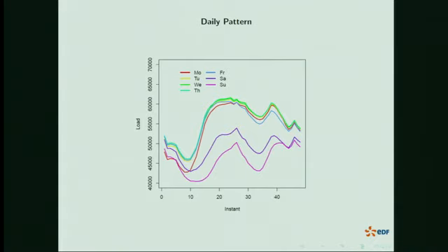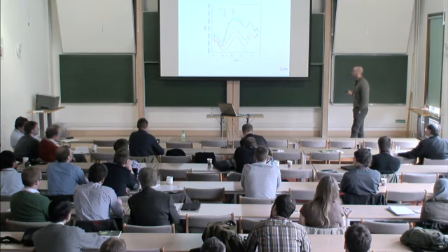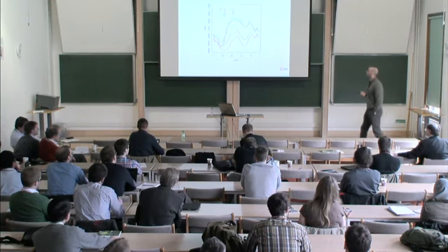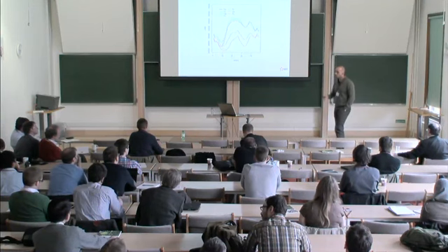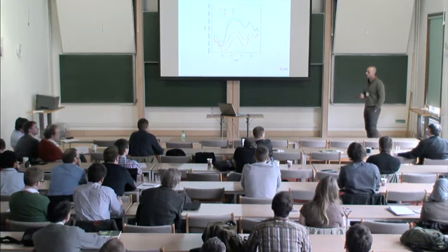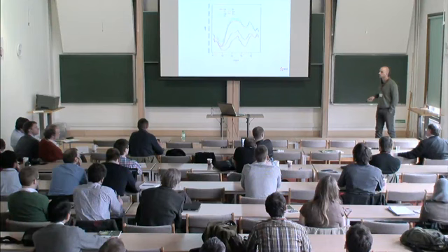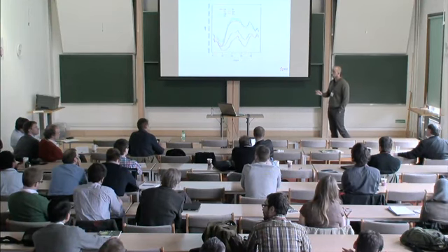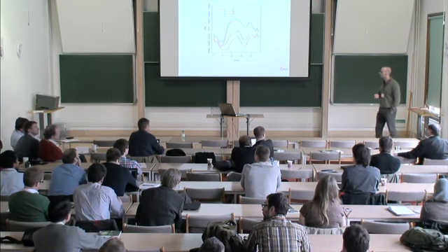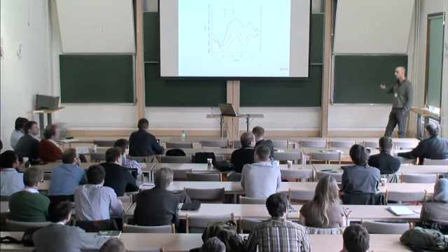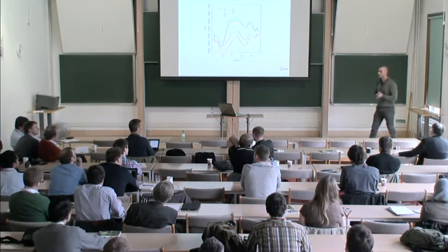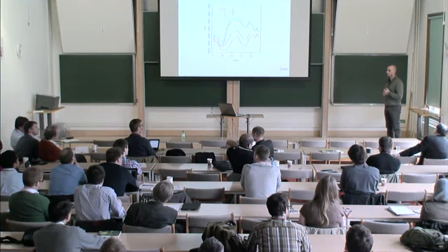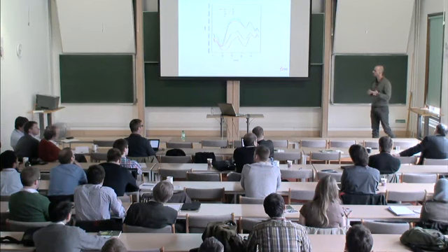Yes. Is there a day-to-day weather variability in the load shape? It could happen. Mostly, for example, if you have one day without any cloud and tomorrow a lot of clouds, then you will probably have a lighting effect in the afternoon, which is totally different between two days. You can also have an impact of temperature variability from one day to another. If you have a big derivative in the temperature, it could have a big impact on the electricity forecast error. It's difficult to forecast something like that.